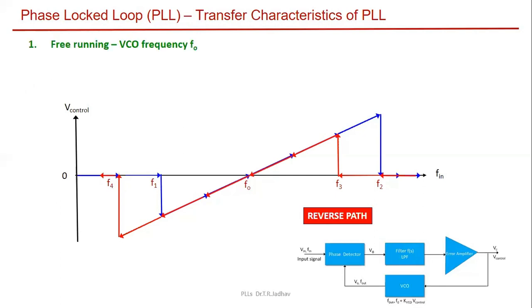Again it enters into free running. So always this flow is there: free running to capture, then once it establishes the lock, it continues in the lock mode, and at the end of the lock mode, it releases the lock and again enters into free running. So hope the whole idea of how the PLL works is very clear.